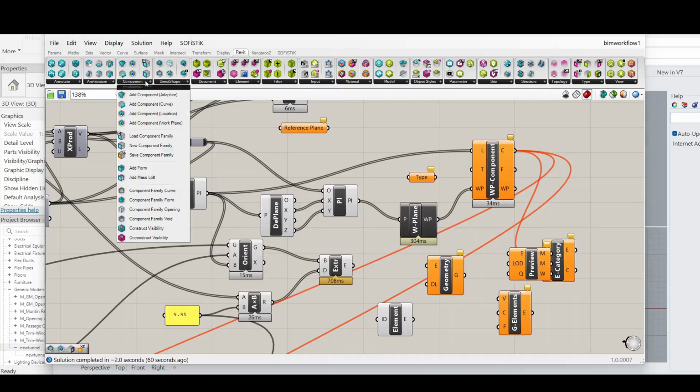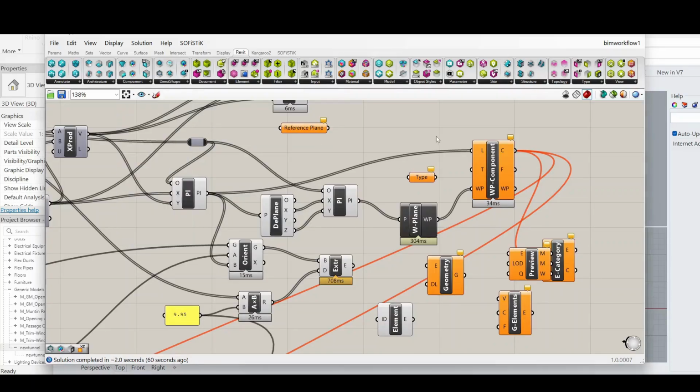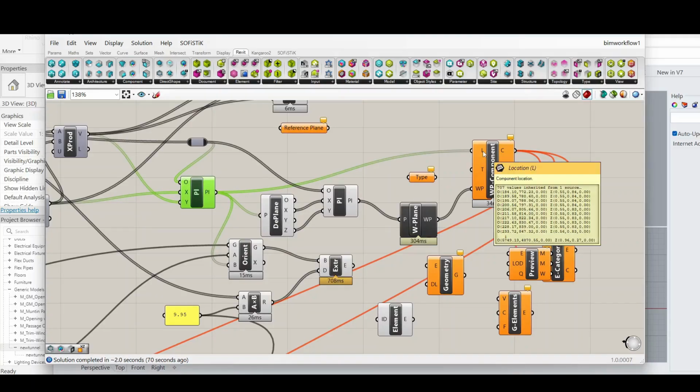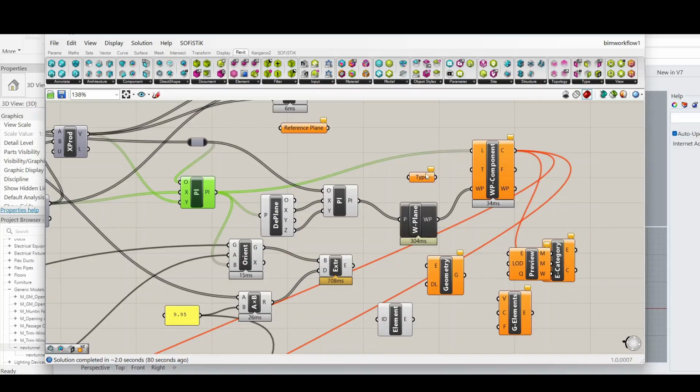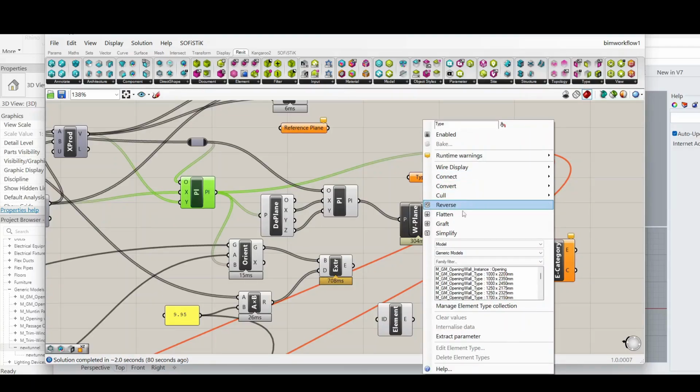Now let's transfer everything to Revit. Inside Grasshopper, under the Rhino Inside Revit components, I used Add Component in Work Plane. Because our Revit family is work plane based, we need to provide the work plane, the family type, and the location. For the type, I selected generic models, the tunnel, the family we created earlier.